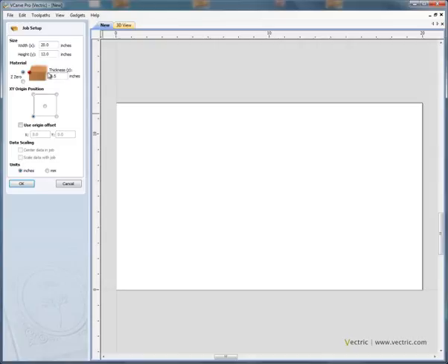Now it's very important to specify where you want the Z0 point to be. This is the point at which, on the CNC machine, you reference the tip or the bottom edge of the cutter so that the Z0 point is known for the CNC machining. So here we'd specify it on the surface of the material, or we could specify Z0 to be on the table of the machine. For most projects, we teach people to use the surface of the material.